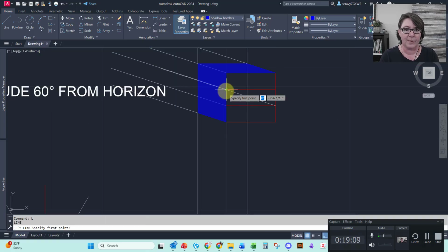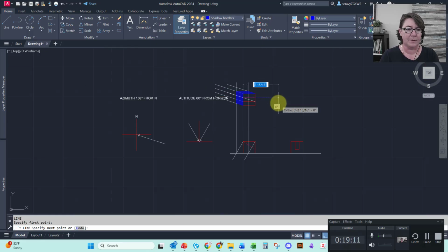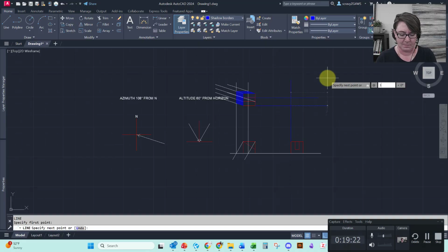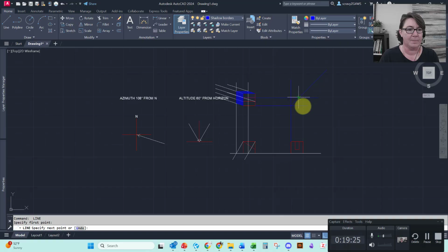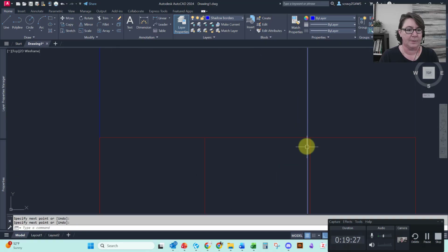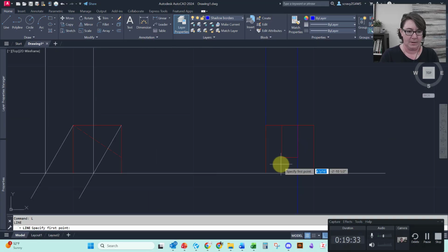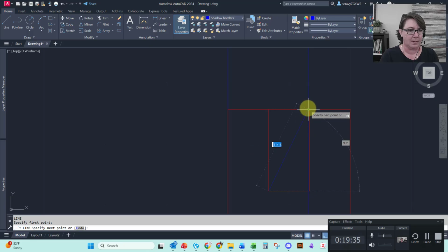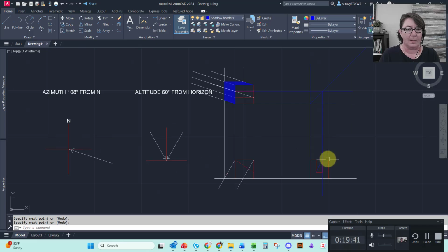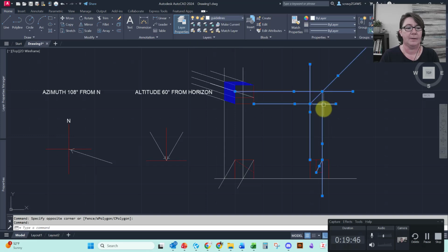What we would do is transfer that measurement by building our 45-degree transfer line. And then that would come down here, and we're interested in this point right there. So we would connect here to there. Just realizing that those should have all been white guidelines.